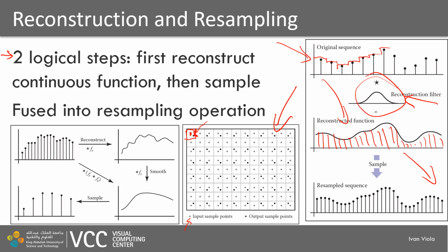If we would do that, we would again create certain aliasing effects, where the higher resolution gives a possibility for higher frequencies to leak into a representation which is then sampled by lower frequency samples, and will create a similar artifact as we have seen in the first example of these sine waves, where a high frequency sine wave was turning into a much lower frequency sine wave with improper dealing with the reconstruction.